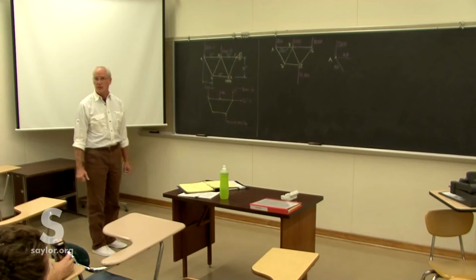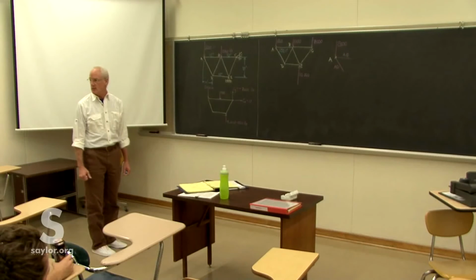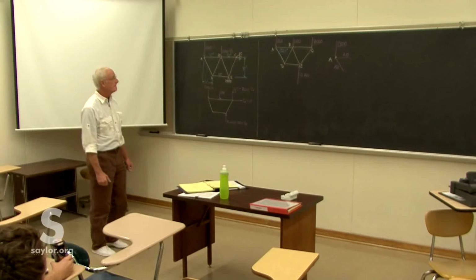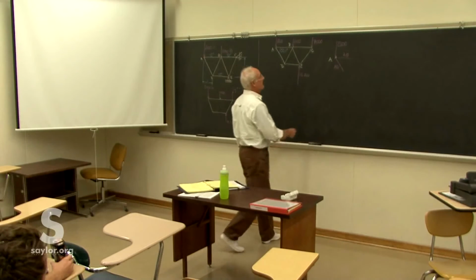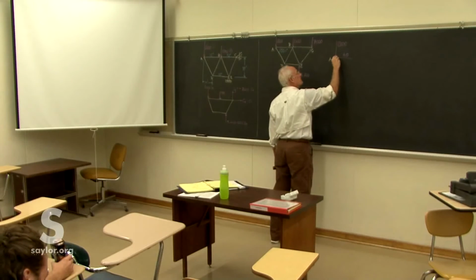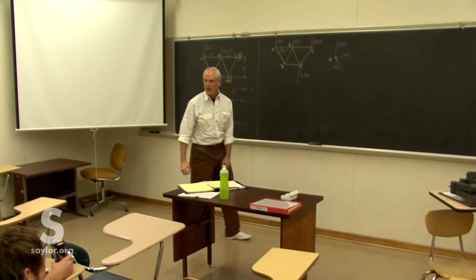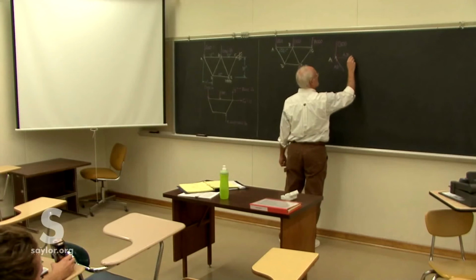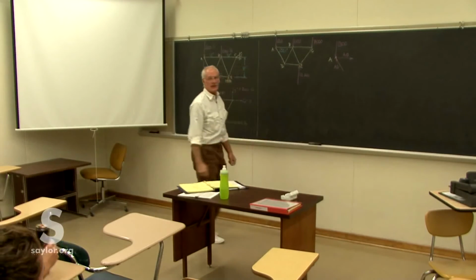But if we do, let's put it in and avoid any minus signs if possible. Which is which? AD is going towards A. I've got some down force. That's the only place I'm going to get some up force, so I know it's got to go that way. And AB is going away. And then that tells me AB has to be going like that.